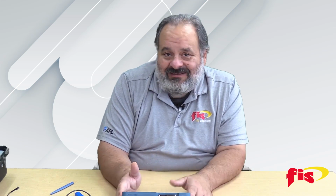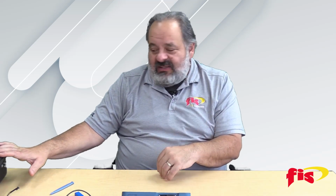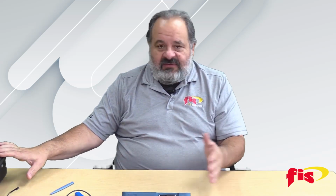Right, we could have fusion splices and bends and stuff in there, but I would say the most important thing that we test in this cable would be the first and last connector, and we need to include those. So I'm going to show you a scan without a launch cable. I have a box of fiber here, about 3.5 kilometers, and I think it's got an event in there. It's got the first and last.